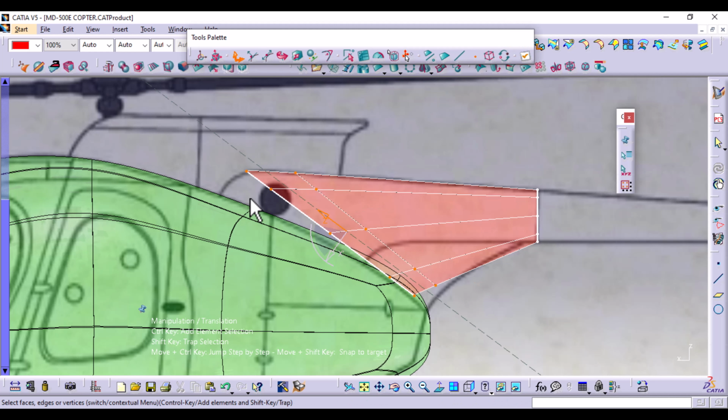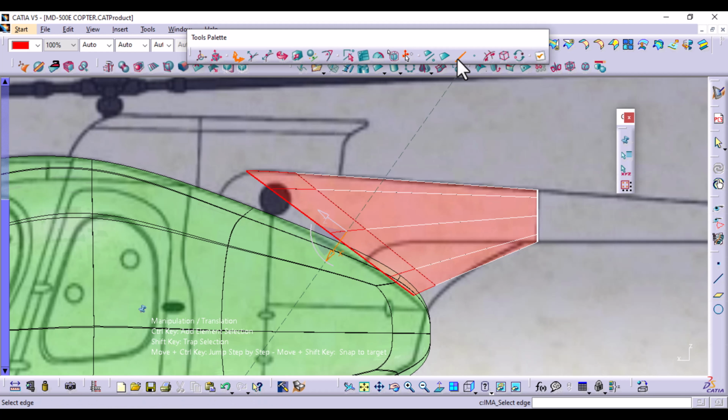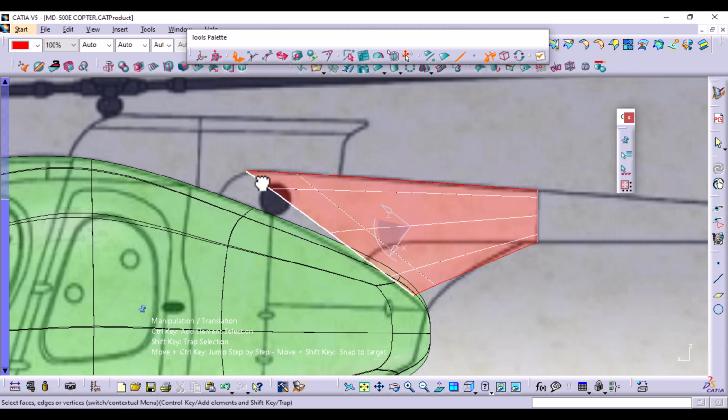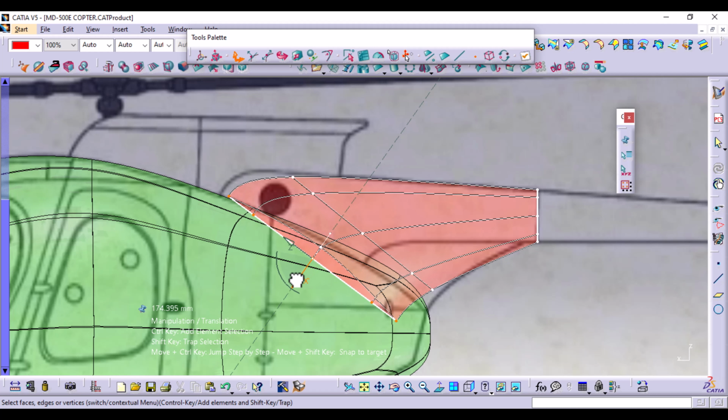Let's go back to translation. Now we need to select this edge at the very end, so you can select edge instead of point, and then select propagation, so that once you select one edge, it should select the entire edge. Just one edge, and you've selected everything. Go back to vertices. You can see it has selected the vertices. Don't reset the robot yet. So while it's still on this orientation, you're going to translate this down like that.